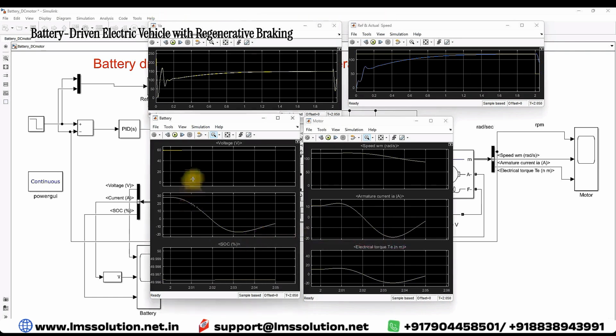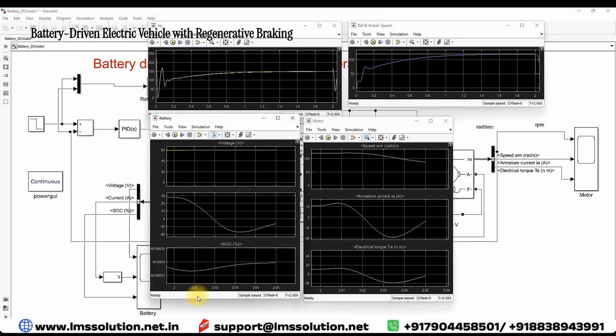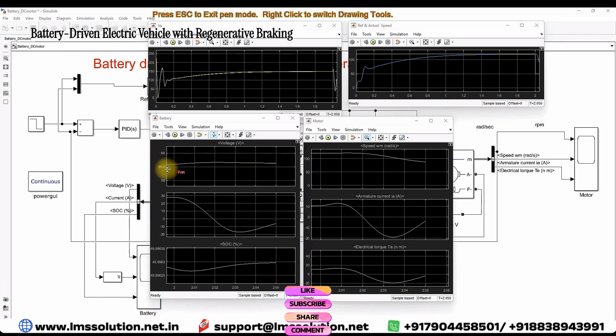And I'm also going to expand that. Yes, you will see it clearly here. Now we can see that the SOC of the battery is increasing because of the regeneration energy. Because of braking, the SOC of the battery is increasing. I also need to check the voltage, whether the voltage is increasing. Here you can see that the voltage of the battery is also increasing because of the regenerative braking.